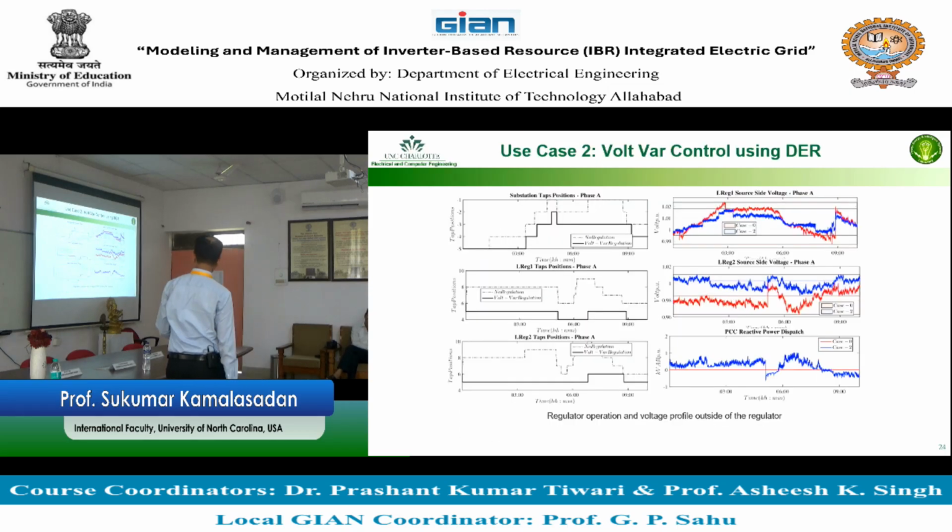When we do the volt-var controller, we are looking at the voltage profile and making sure that the voltage profile is within the band. We are also looking at the step change in the transformer taps. So this is without control, this is with control. You'll see the taps are shifted. That's one observation. Second observation, some of the taps are not happening.